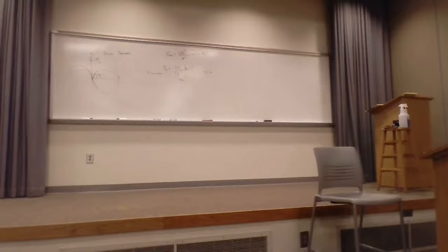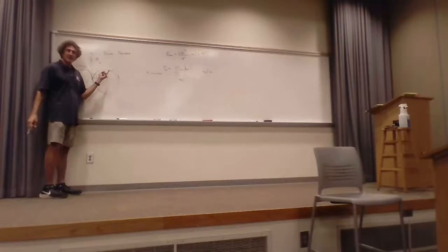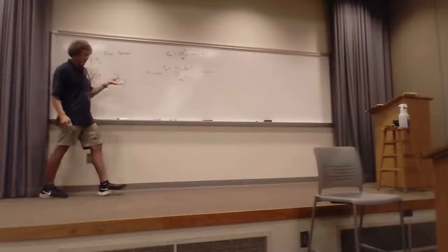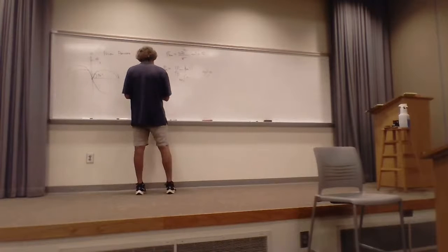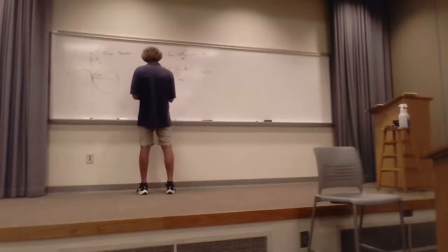Now, sometimes what they'll do is plot this in dB, and then it makes sense to do it logarithmically. And they'll have the power pattern right here as a function of angle, the average power, and it'll be normalized to P max, but it'll be in dB. And you'll see stuff like this.